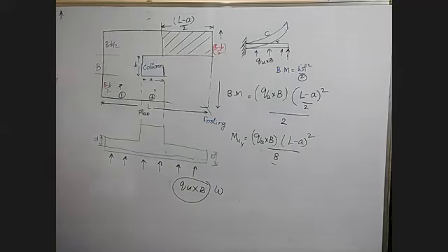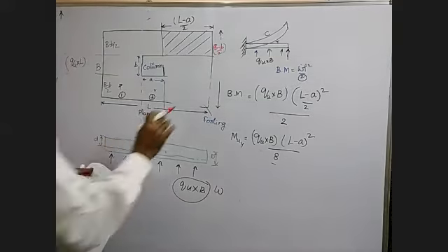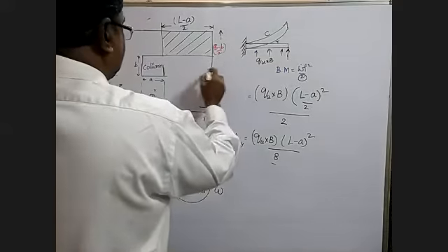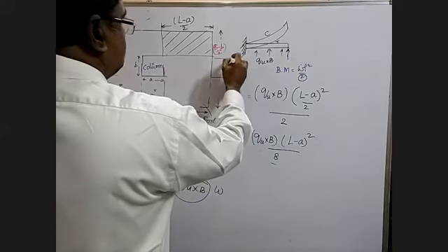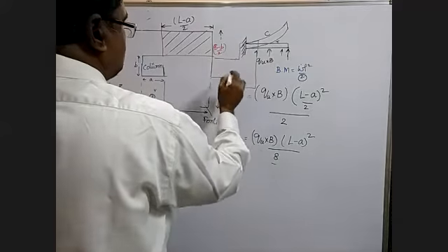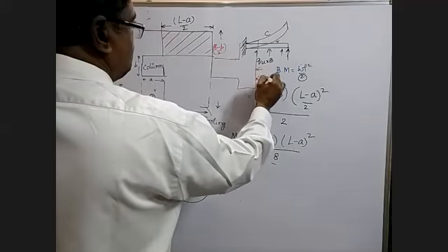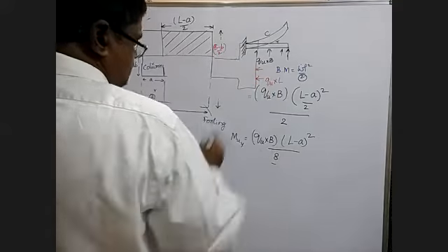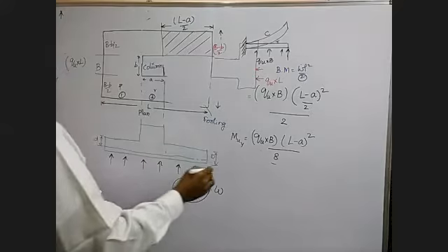So if you want the bending moment in the x direction, earlier we said Q into B, and in this direction it will be Q into L. If we draw the same diagram in this direction, here the soil pressure is QU into L. So for the same thing, repeat this procedure.